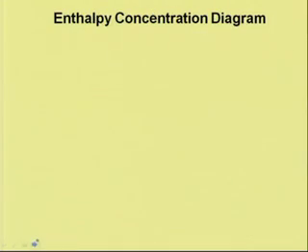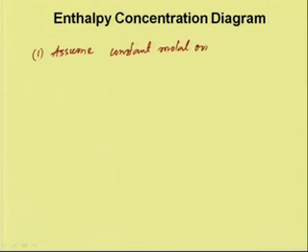So, now we will discuss another important equilibrium diagram which is required for the distillation calculations, the enthalpy concentration diagram. In general, in a distillation calculation, we assume constant molal overflow for a distillation column design.